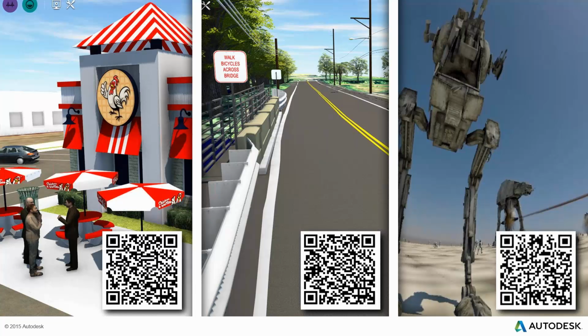He brought that mesh environment, I think it was like 85 acres, into InfraWorks and then passed that through into Navisworks and created the VR stereo panorama of that, so you could go out and shoot the site and actually be standing on the site and be able to look around. And let me say this, since that did come up, we noticed another caveat with that.